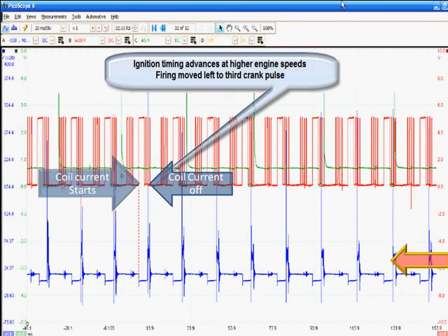That's our spark. As we go across here, are all those sparks doing the same thing? No, they're not. They're telling me I've got some dirty injectors. They're telling me I've got maybe a bad plug wire. I'm not sure. I've got some things going on down there, but definitely dirty injectors.